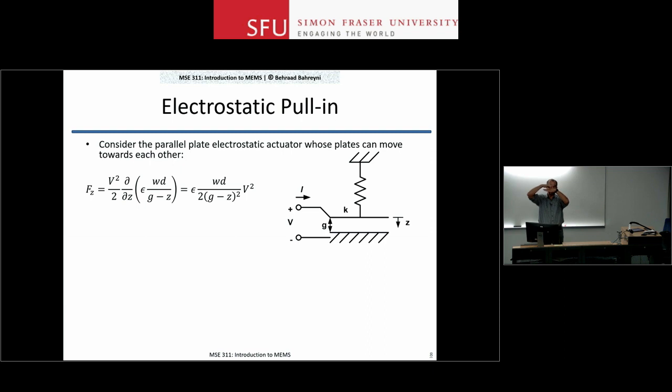So this electrode that, let's say you're holding it up with a spring, it saw an initial force of, let's say, 1 nanonewton, came closer to the bottom electrode, but now all of a sudden the force is not 1 nanonewton anymore. Because the gap is smaller, because dC/dy is bigger, now let's say you see 1.5 nanonewtons.